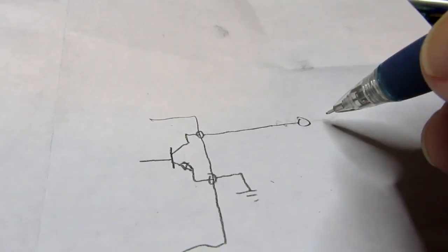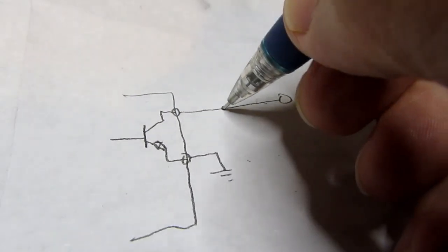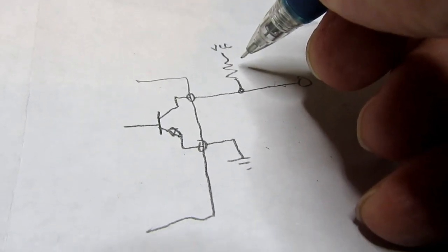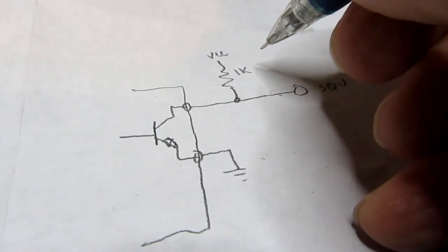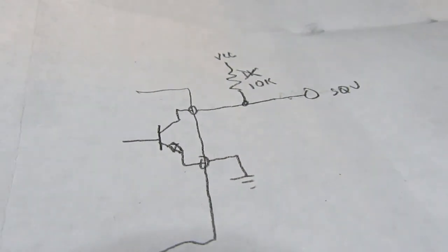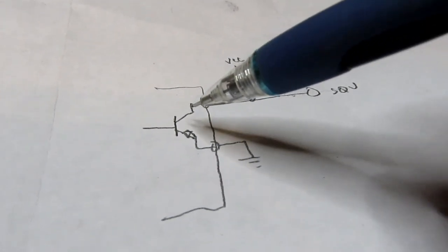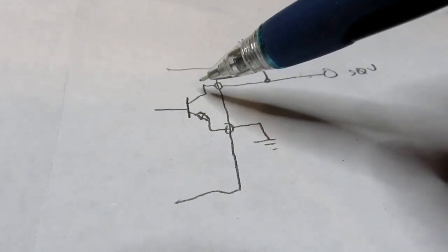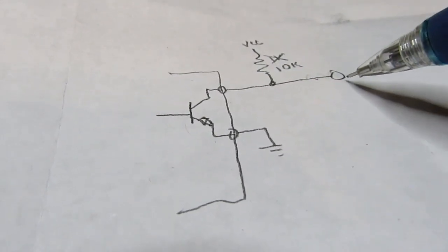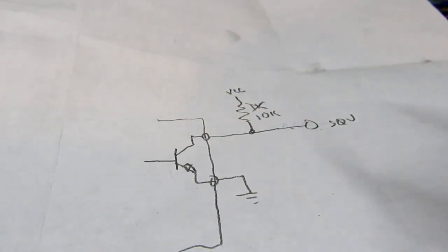It goes to the square wave output terminal, and then there's this resistor going to VCC. And this should not be the 1K that's provided with the kit. It should be a 10K resistor according to the XR spec sheet. So the way this works is when this transistor is off, it's like an open circuit. It's an open collector, as they would call it. And the resistor pulls the square wave output pin up to whatever VCC is. In the case of my kit, I'm running it at 9 volts.